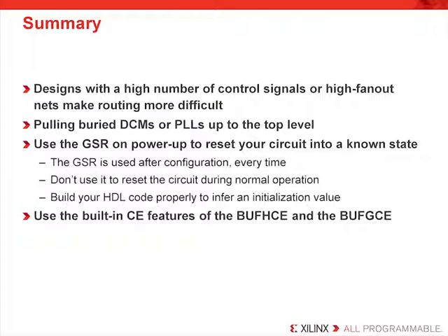So, also keep in mind, don't use the GSR to reset the circuit during normal operation. This is not recommended, even though it's still supported. And build your HDL code to properly infer an initialization value so you come up in a known state. Also, use the built-in clock enable features, the BUFH CE and the BUFG CE, so that you can save routing a secondary clock enable on general interconnect.